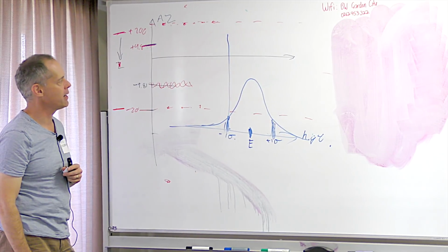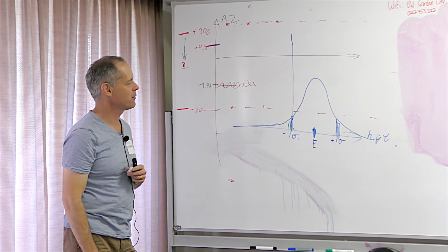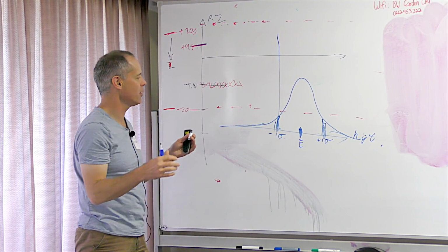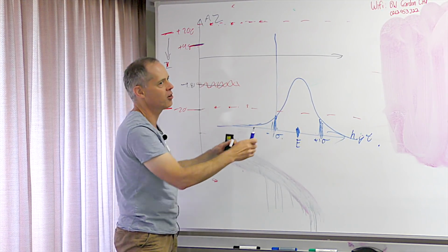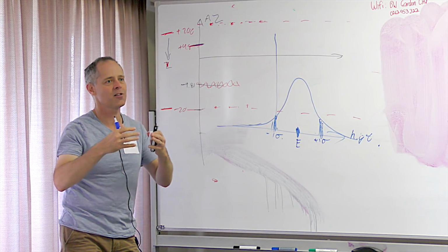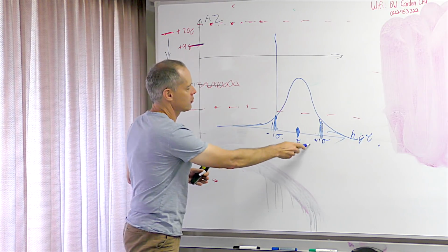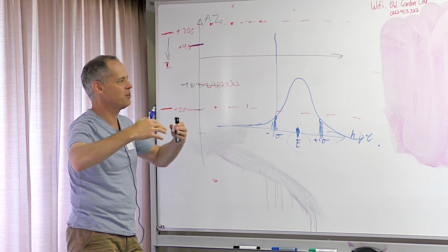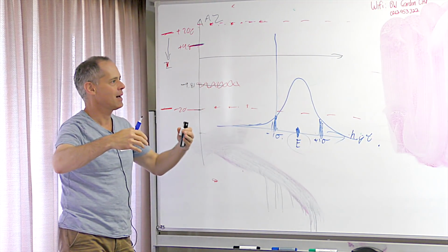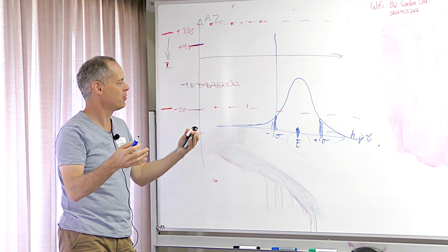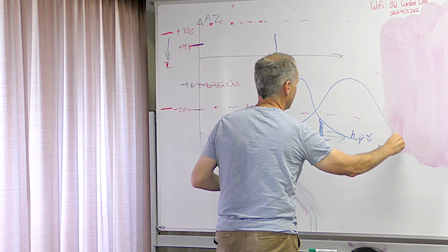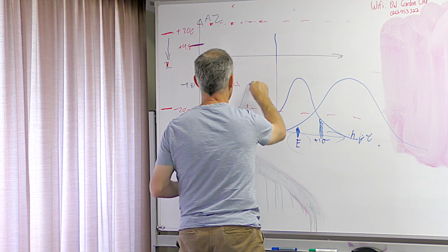What you do with the UKF is you still make an assumption about errors. So this is my error distribution at this point in time. Now I'm going to do some mathematical operations using this height, and it's going to be predicted forward in time. After I've predicted it forward in time, it's going to have a different error distribution. It might look like that, or it might look like that.